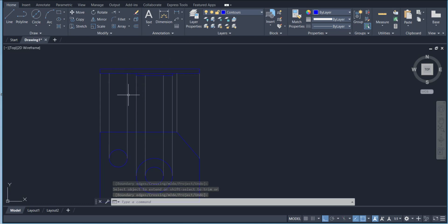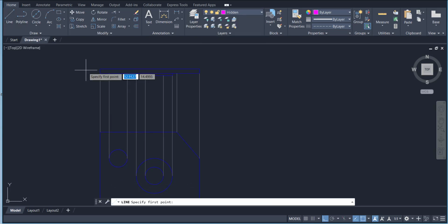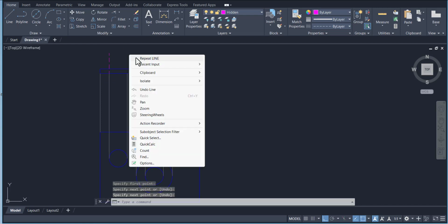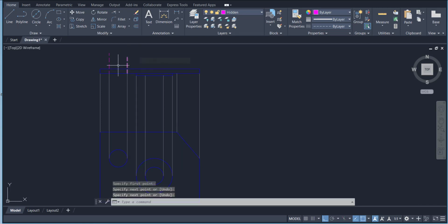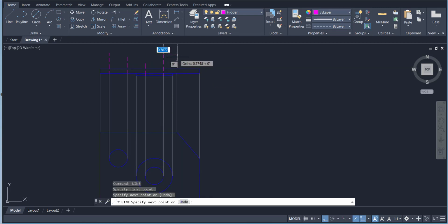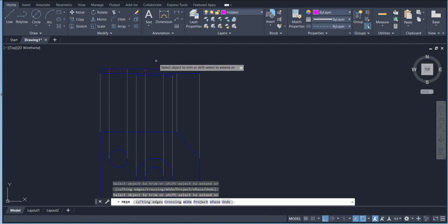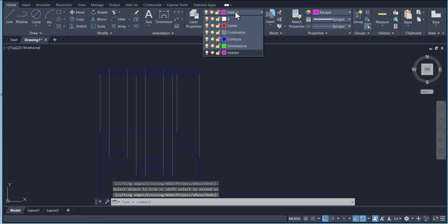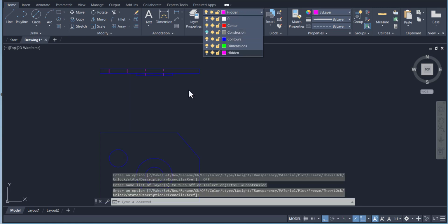And here you can see for this circle from the top we cannot see it, so it's hidden. So I'm going to go to hidden lines, and from this point I am going to draw a line, and again from this point, and this extra portion we are going to trim, again line, and this circle, this inner hole, we are not able to see it. So like that, and like that, and now just use trim on all of this portion, this one, and here you can see our drawing is complete. If I hide the construction, here we have this.